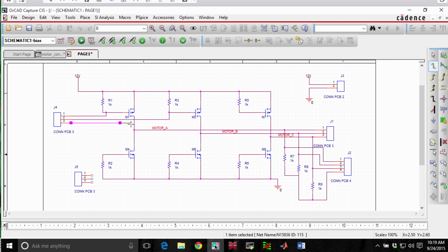Now, every once in a while, OrCAD gets it into its head that it's going to try to connect things for you, and sometimes we just don't want that. Part of what's going on is this wire would actually cut across the actual node junction right there. So I actually have to bring it down, or bring it all the way up. And now it's starting to get really confusing. Now we have wires jumping all over wires. That just doesn't appeal to clarity. So instead, I think we're at a point where maybe what we should do is use connectors.